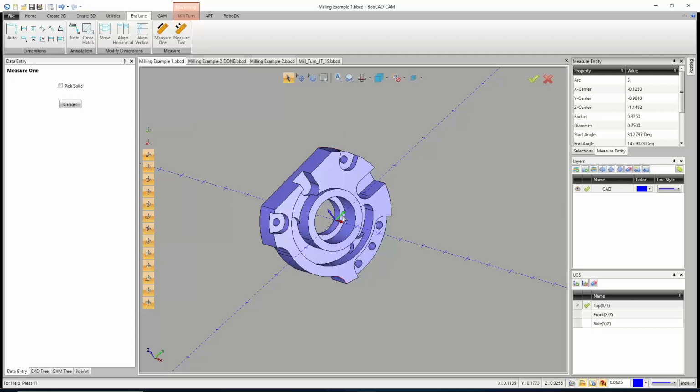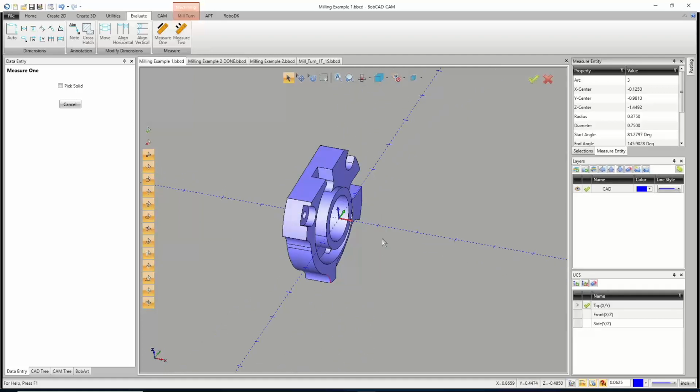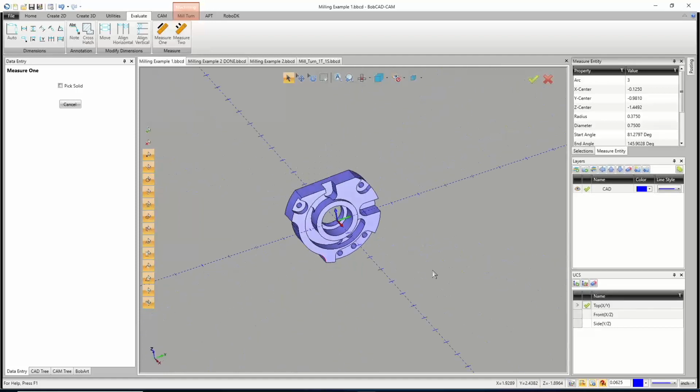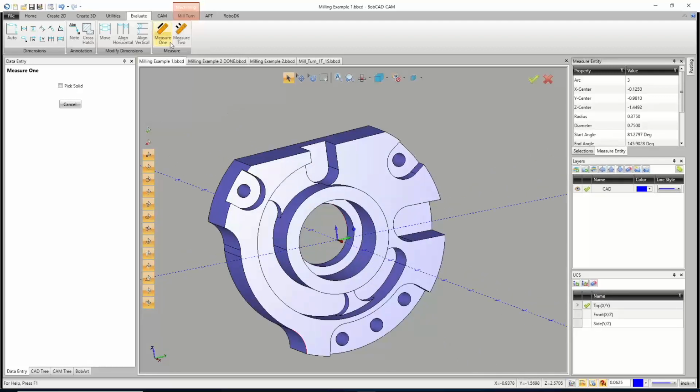So there we have it. I think that's all the tools we actually need. A 3/16 drill. We've got our 1/2 inch spot drill to do the holes. And let's go ahead and do one other big one. Let's take a measurement of this big hole on the inside here, and we'll see that's .875.